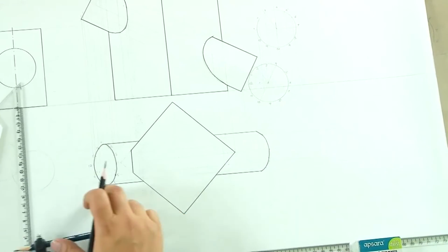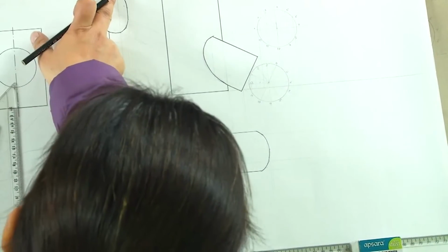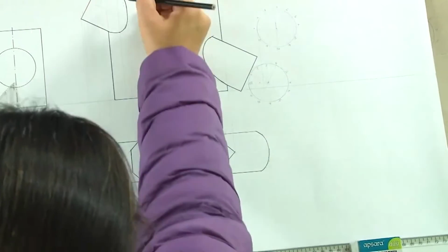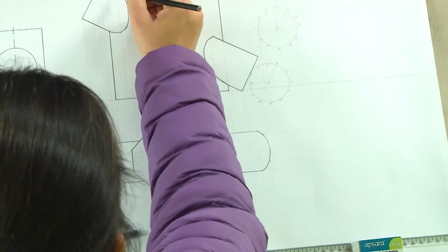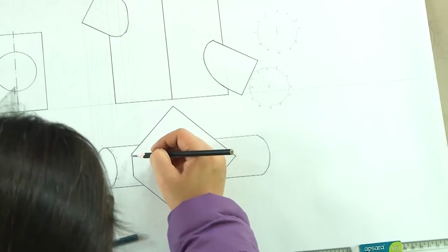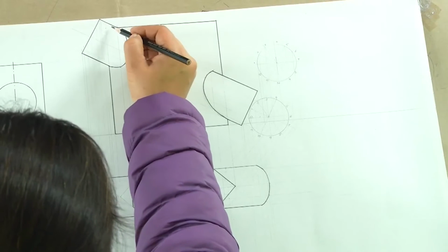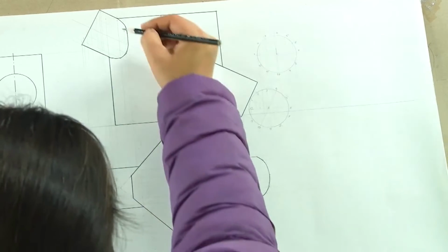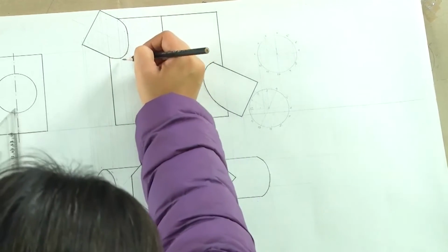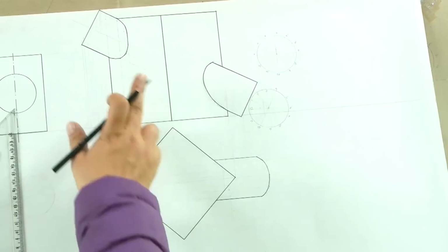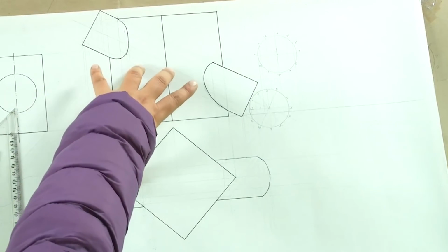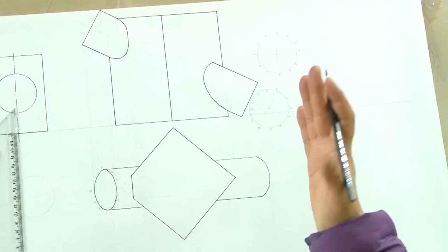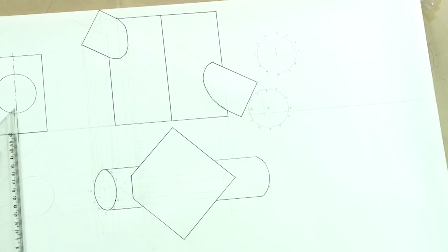So, in this manner, if you look at this, now there was an abrupt end to these 2 points which was on the top. So, which is what we got here. Otherwise, we should have actually got the point somewhere here. So, now since it was cutting it, it was abrupt, and that is why we got a straight line, and from there the rest of the elliptical, the curvilinear surface would start. So, that is how the cylinder would look when we see it from the top and when we see it from the front. That is how the orthographic projection of this intersection is going to come.